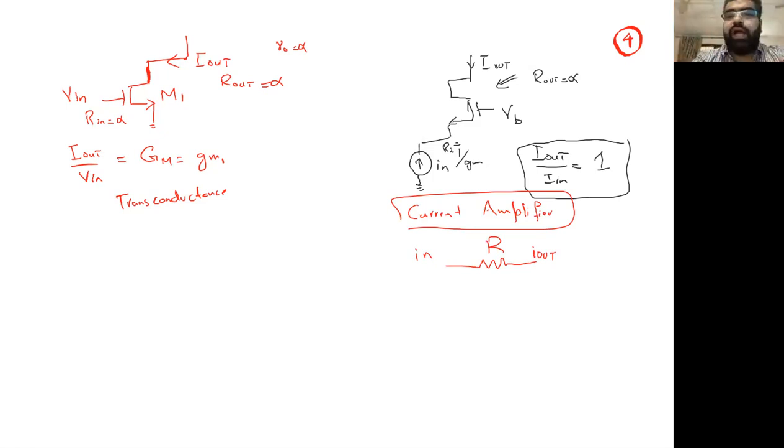For example, if we have this configuration, okay, I in, and we are feeding a system which has parasitic capacitance or some capacitance being formed, which is a common thing. And we have some load resistance RD, and we have output V out. What's going to happen if CP has some value, and RD is a bigger value? We want RD to be a very big value.